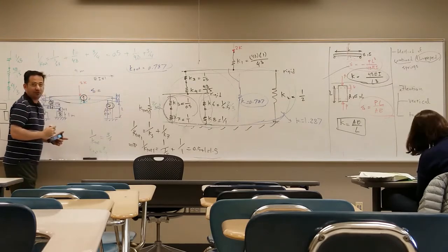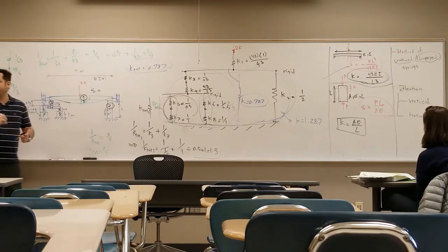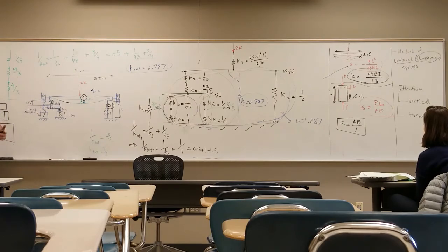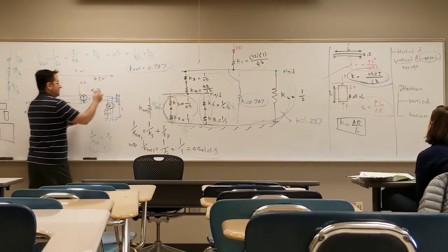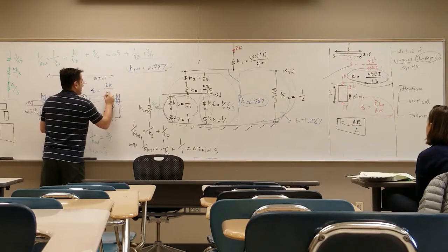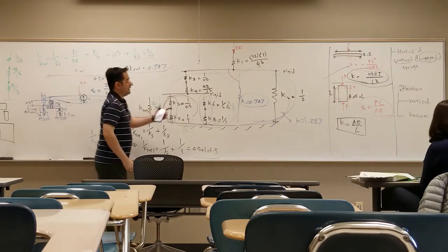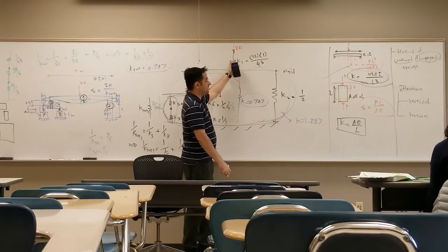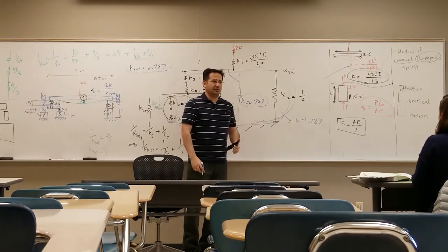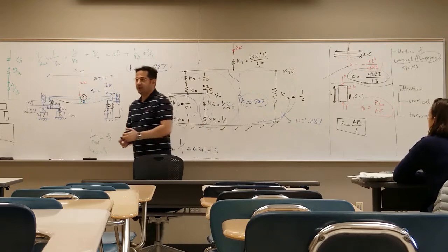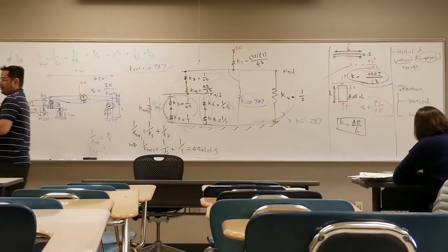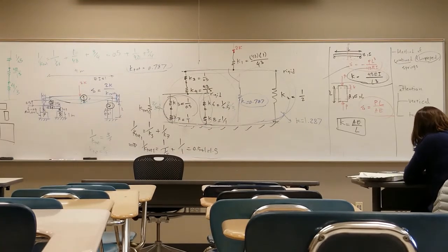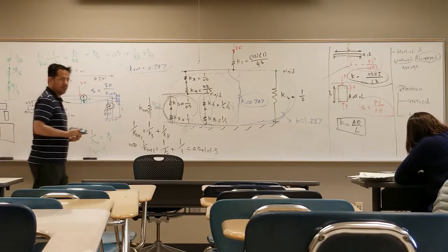Delta deflection is equal to P. What is P? 2K, right? 2K divided by K total, whatever it comes. And what is K total? It comes from series addition of this big spring to that. You see? So this problem is probably the most complicated. You know, they use software to do that. But you can use the method of combined springs to quickly calculate it.